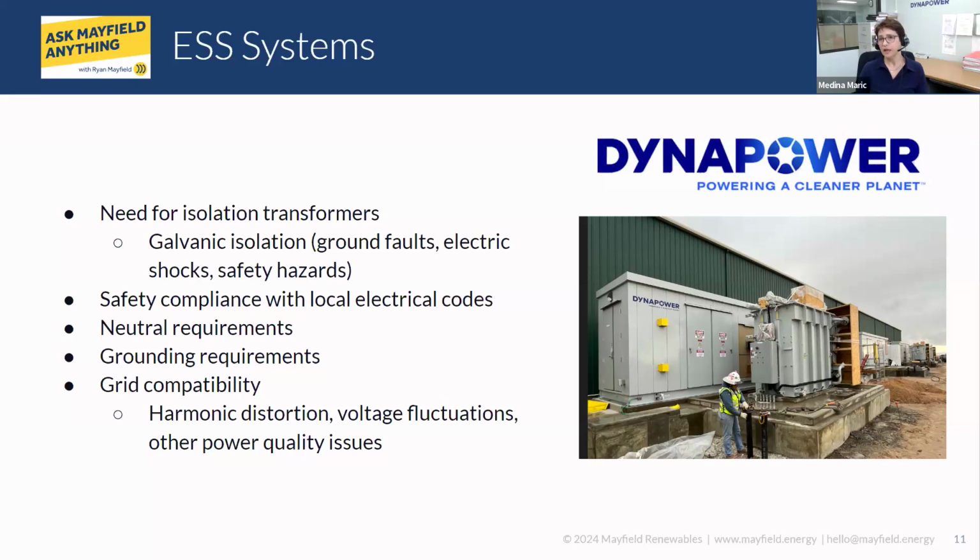Some inverters will have neutral, some will have grounded neutral, but in general, none of that. And if that neutral is grounded on a PV or an inverter or a microgrid, that can create a lot of problems, because it closes the ground loop and provides a path for return current that can be quite high. So that becomes a problem.